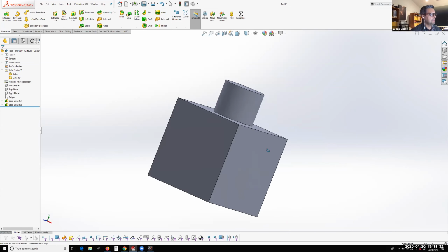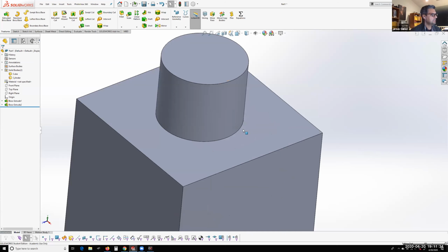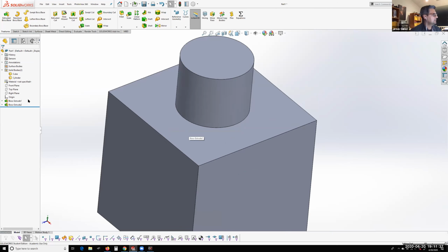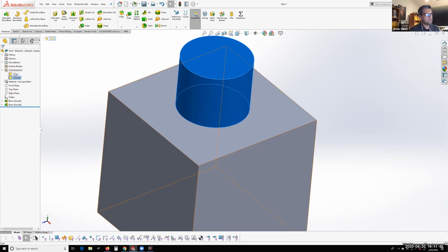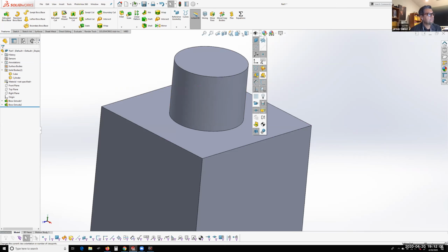All right, so here I have two solid bodies not merged, and I can look up here in my folder and it says 2. So by having the folder open, you can keep track of your bodies and what's going on with your part. Because sometimes you may have wanted everything to be merged, but you may have inadvertently clicked the merge off, or maybe you wanted it merged or not merged and you clicked on merged, or you left that on. So by looking at the folders, you can see that there's two separate bodies, whether intended or not.